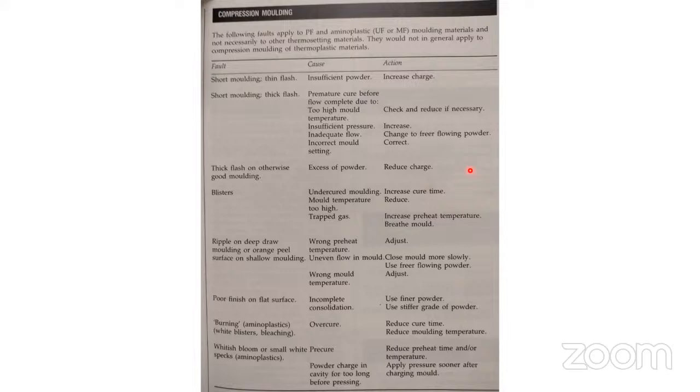And one more thing, if I compare in terms of cost, compared to injection molding, which one will be less costly, part cost or overall? Injection molding is always better as compared to compression. But why do we go for compression? If you want a stronger article with low shrinkage, low warpage, and quality, then you go for compression molding. If you want durability, then you think about compression.